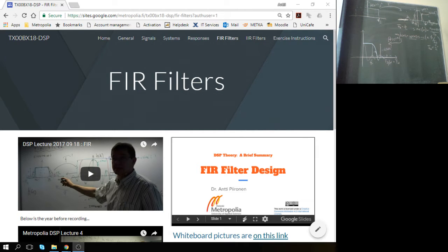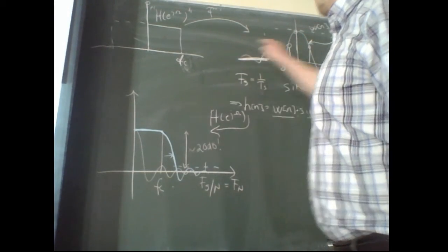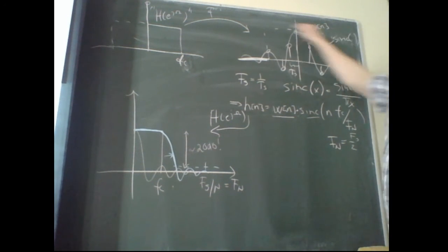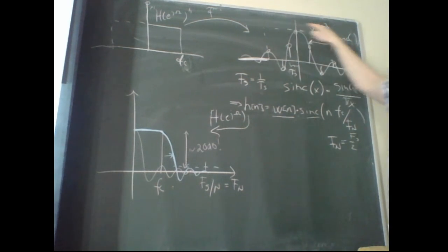Well, it's also the same as the attenuation of a running average filter. You don't get much better than that if you look at the definition of the low-pass filter. Okay, so that's the attenuation of that window, which is basically the same as the average filter impulse response.